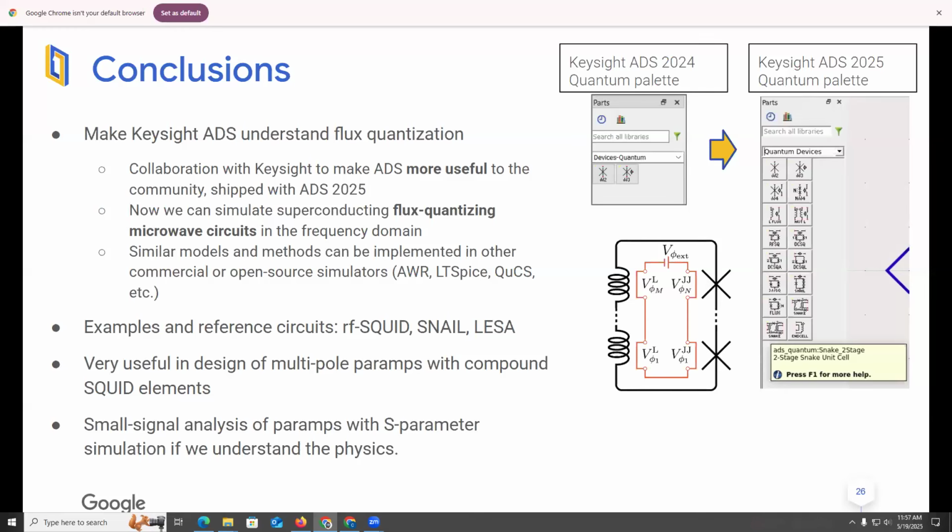Do the time domain simulation starting from everything quiescent, everything is zero, and you'll get the correct result. So that's the difference here. Time domain simulations natively follow the rules of Maxwell equations, which will give you flux quantization if you're starting from something consistent. Frequency domain simulations won't, because they just apply the voltage and find the solution that's consistent with that voltage. Without the constraint of flux quantization, you don't know where you are.